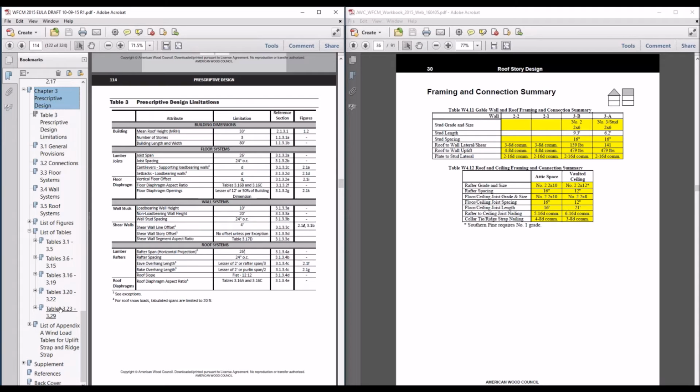And there's an interpretation we got from ASCE 7 that the component and cladding bending loads always control within the limitations that we've put on the Wood Frame Construction Manual. I'd venture to say, unless you've got some really heavy axial loads, it's going to control in most cases. So those are the two different load cases we evaluated, but component and cladding loads, bending only, is what controls, and that's what those tables are based on.